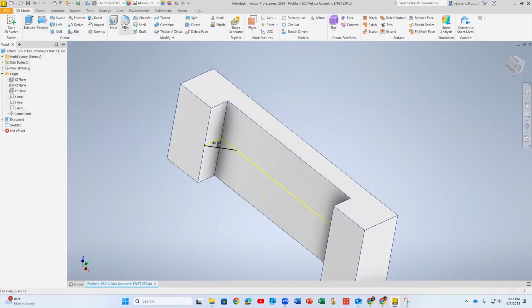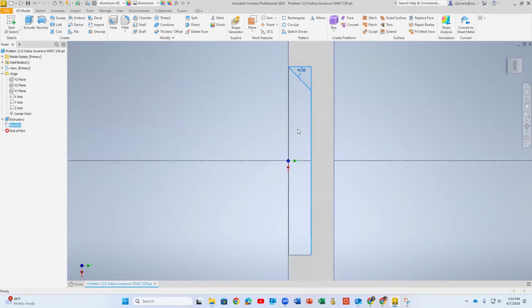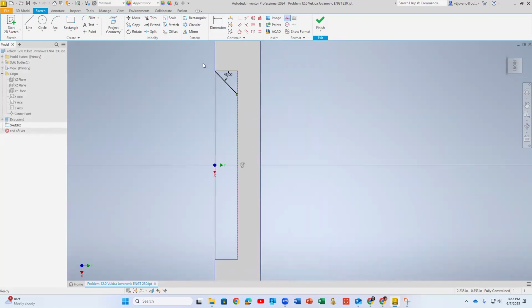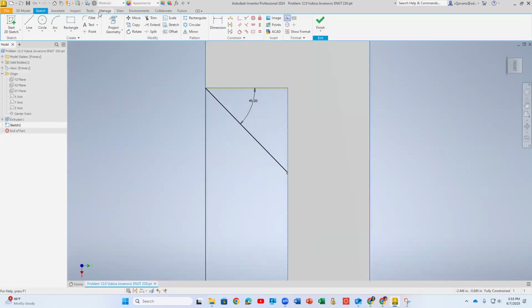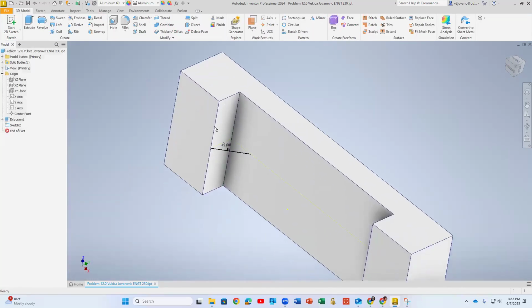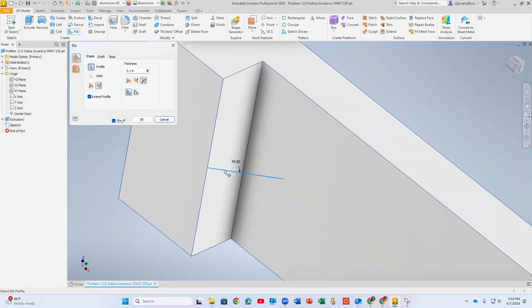And if I want to create a rib, let me see what kind of thing it's asking me. So my profile is that, oh, it's an invalid loop because there's one extra line. I have to go back and make sure that this is construction, and maybe just put these two. I think sometimes it works only with a line. So let me see, I'm not sure in this software, honestly. I didn't use it for a while. So you see, I put that.